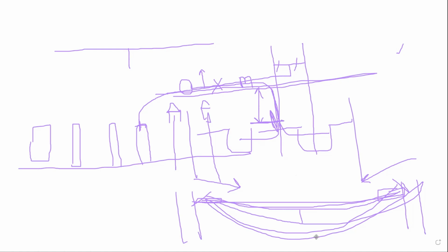It is free and it will move due to the wind. And the sag will increase due to the temperature rise, because the length of the conductor increases. If the length of the conductor increases, the sag will increase. If the sag increases, tension will increase. So all these conditions we have to consider when calculating the sag here.